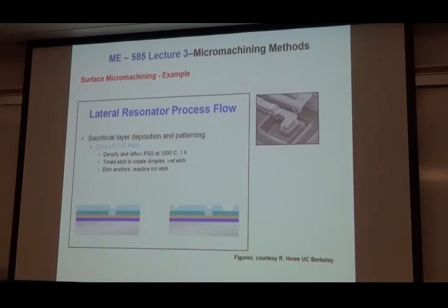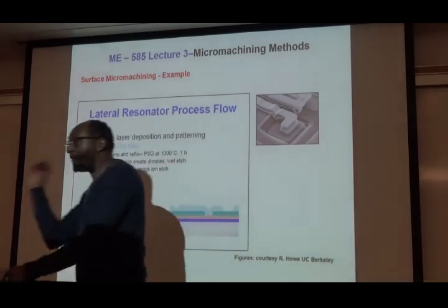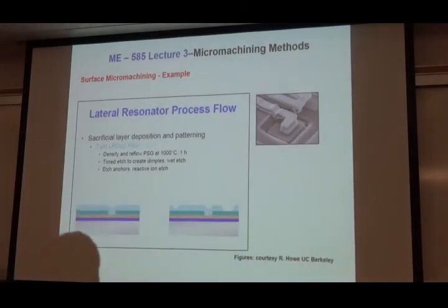It's going to be etched away very easily with hydrochloric acid or sulfuric acid or any of the acids. So what we do is we deposit this 2 micron layer, very thick. So far what you have seen is 0.15 micron, 0.2 micron, very small. But now, being brave, 2 microns of PSG.